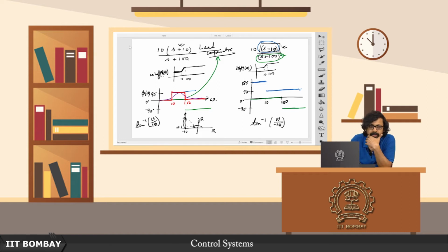So the resultant plot here would look something like this. Let me use the red ink. Initially this green factor is contributing 0, the blue factor is contributing 180, so it stays like this, and then suddenly this fellow contributes a little less, it contributes 90 thereafter. So you immediately have a jump here, then it comes to this 90, and at this point suddenly this fellow shows up.